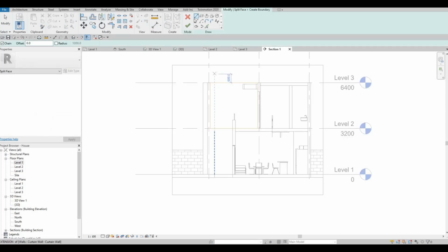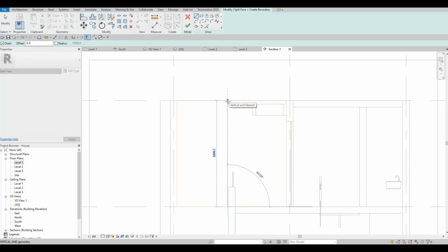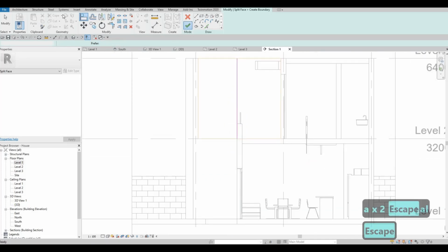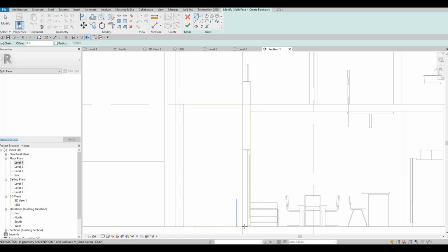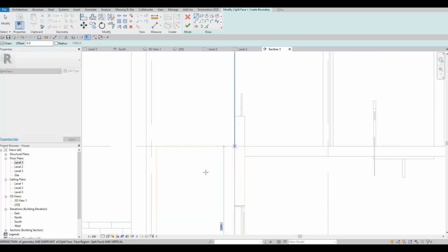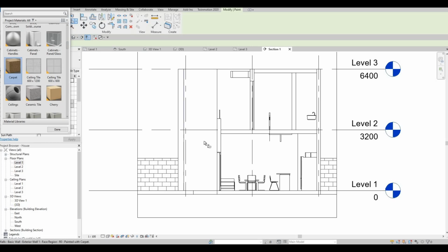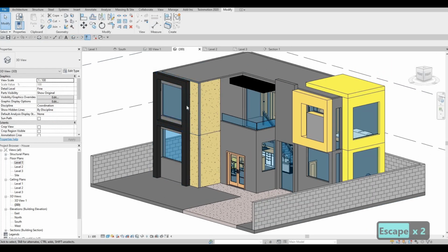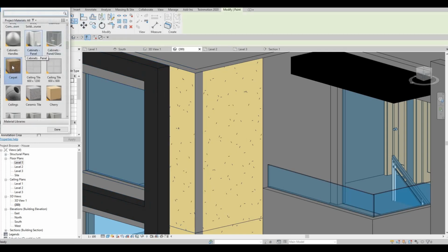So split face, this face, click on this and go all the way up. But as you can see, we just need to align it better. So AL and then finish. Split face again. This one. And then click on align. Click finish and then paint again. And there. Look at it in 3D and it will look like that. Here we're just gonna paint this face.